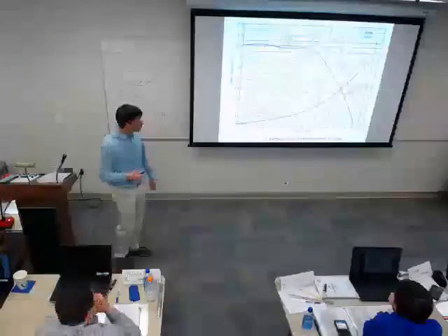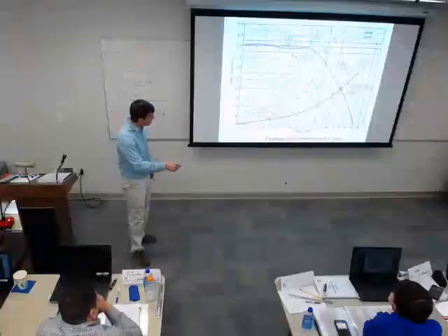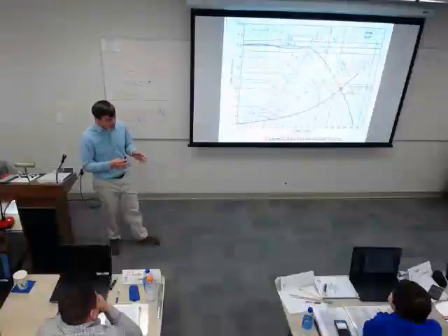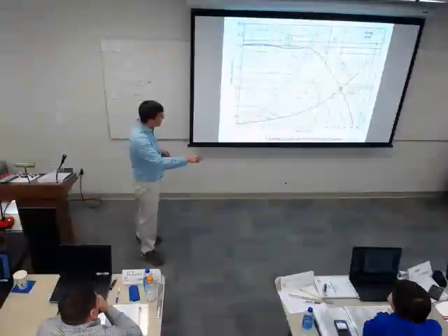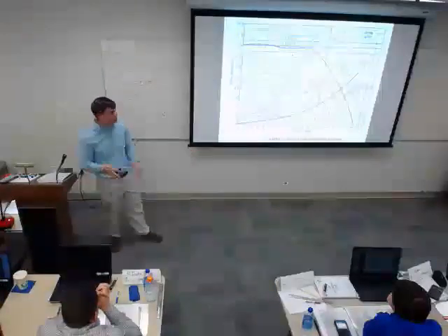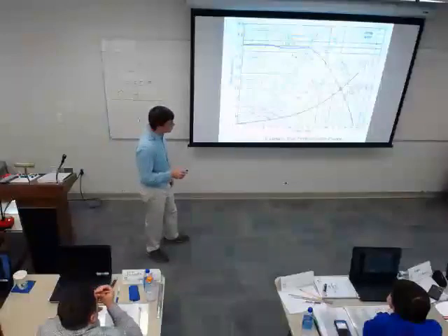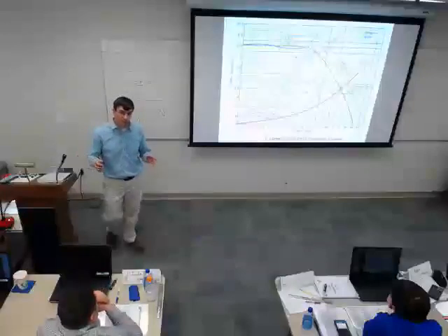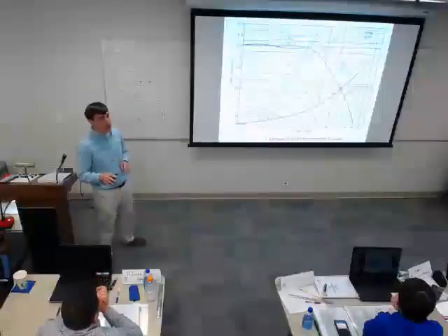So I talked earlier about the system curve. The system curve is dictated by the ductwork and all the fittings I talked about. Basically, there's a squared relationship. I'm going to show you that in a minute, but if my damper positions don't change, my system curve doesn't change. It is set. You can equate it to one big fixed orifice. It's one set pressure loss through that system if my damper positions don't change.